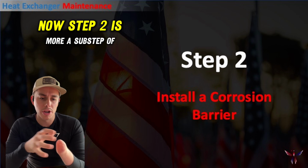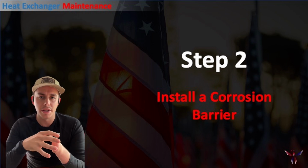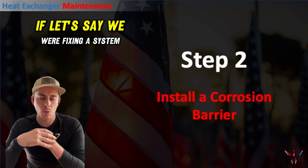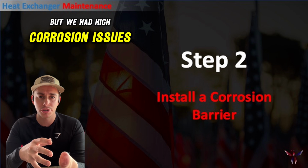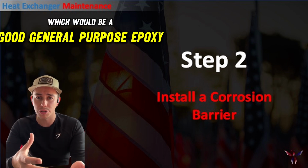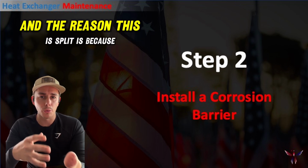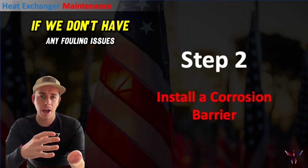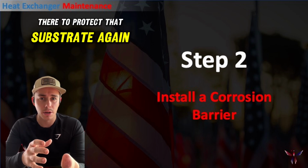Now, step 2 is more a sub-step of step 1, but I split it up. Let's say we were fixing a system where we didn't have any fouling issues, but we had high corrosion issues, we could switch to just a corrosion barrier, which would be a good general purpose epoxy that can handle the water or anything that's in there. The reason this is split is because if we don't have any fouling issues, we still want a corrosion barrier there to protect that substrate.